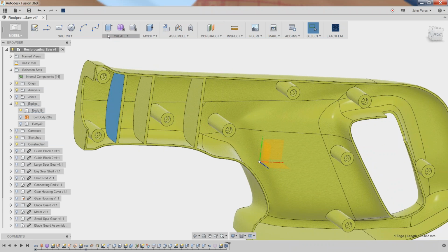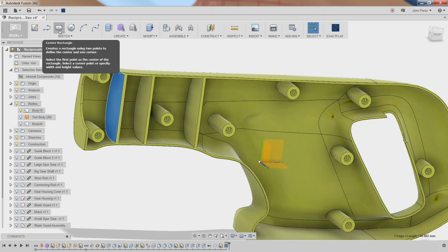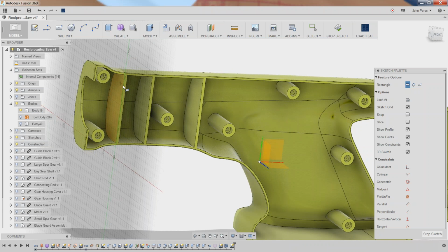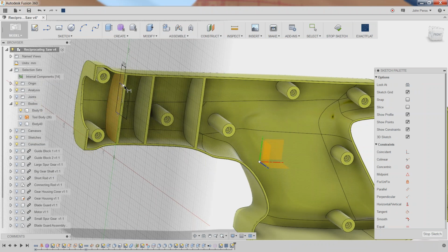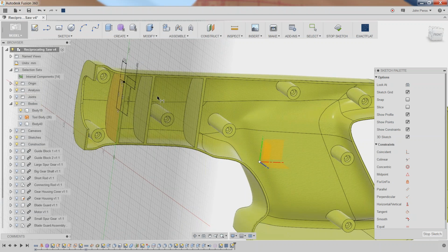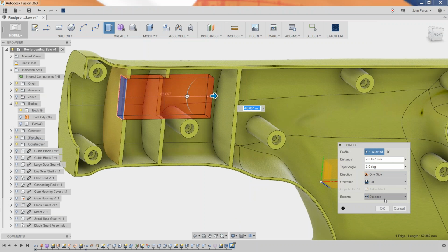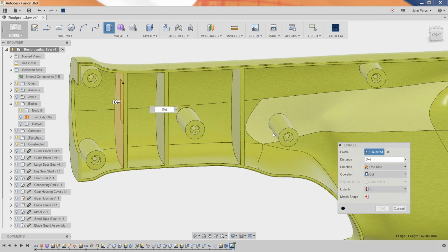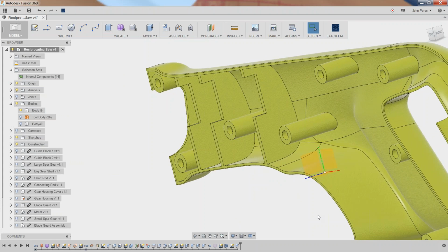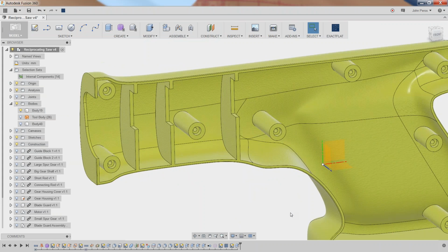on here. So in order for the internal components to fit, we're actually going to need to create a cutout on these ribs. Notice that one of the things in my sketching environment is that I can actually dimension while I'm doing the sketches, which is kind of nice. It gives you a little bit better speed if you like to do that in your sketching environment. So I've got my dimensions all set out there, and I can do my typical extrude. You know, we've got a full parametric system in here, so if I want to extrude up to a face and create that relationship, this is stuff that you guys are very used to.